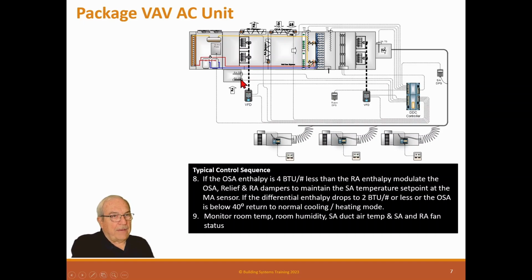So what happens if these get out of calibration differently than the outside air sensors, now you can get the economizer working when it should not be, or not working when it should be, thus not saving the energy it's supposed to. So enthalpy economizers are much more problematic to keep operating than a simple dry bulb economizer.